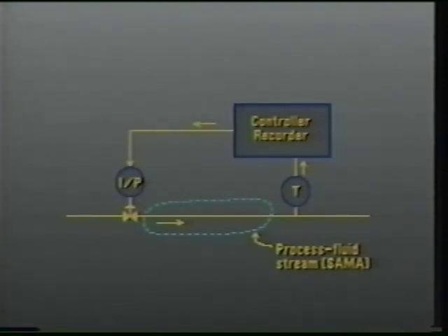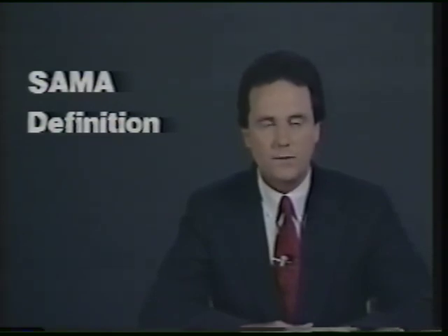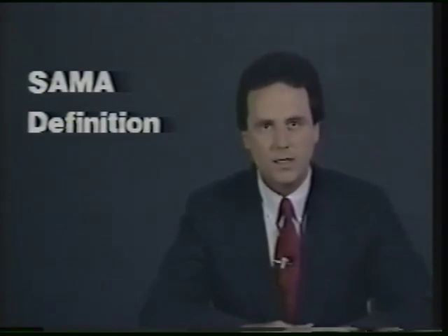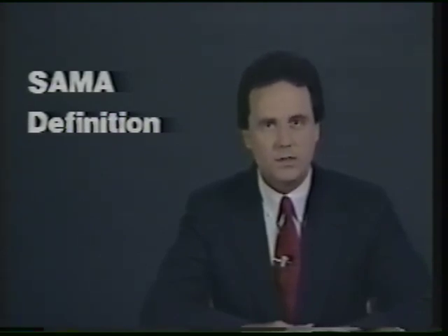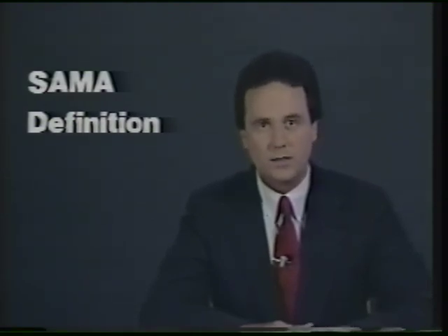Another definition, as set forth by SAMA standards, considers the process to include only the fluid stream within its piping constraints. Obviously, this description would have to include information about the geometry of the containing vessel, properties of the fluid, and the manner in which the containing vessel relates and interacts with its environment. While this definition is perhaps the purest and cleanest means of considering the concept of a process, it presents difficulties in measurements and therefore is not the most practical and can create problems in the design of control strategy.